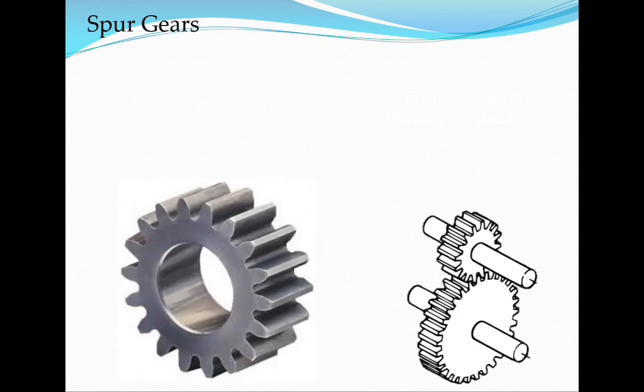So now you see this is a spur gear. Why do I say this is a spur gear? You see the teeth here. The teeth of the spur gears are straight. It has no helix angle. And the best part of the spur gear, the characteristic of spur gears, is that it is very easy to manufacture as there is no helix angle. And it is a very common type of gear with very high efficiency. However, the demerit, the disadvantage, is that when it operates, it normally produces high noise compared with helical gears. Why? I'm just explaining here.